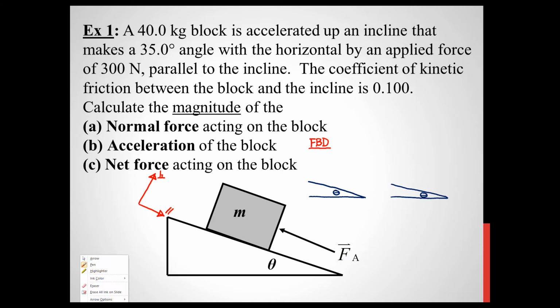Now, I've drawn that in blue because technically, again, on a free body diagram, you're not supposed to show other surfaces or objects that your main object of interest is in contact with. Okay, so let's draw the blocks now. May as well do the mass acceleration diagram first because it's a lot easier. I have a mass, and we're pushing this thing up the incline, so my acceleration is going to be up the inclined plane.